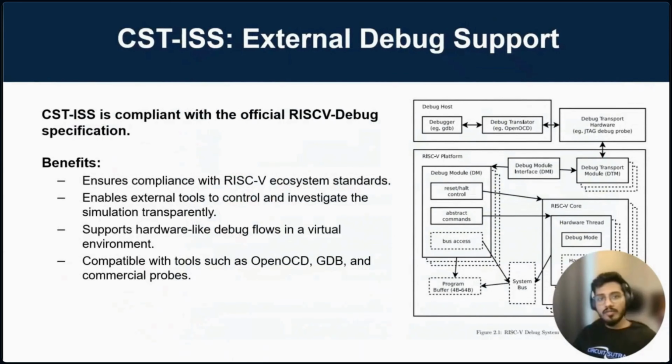So beyond GDB, we are fully compliant with the official RISC-V debug specification. This ensures that our virtual environment behaves exactly like real hardware, as described in the RISC-V specs. CST-ISS is compatible with standard ecosystem tools like OpenOCD and commercial debug probes, allowing external tools to control and investigate the simulation transparently.